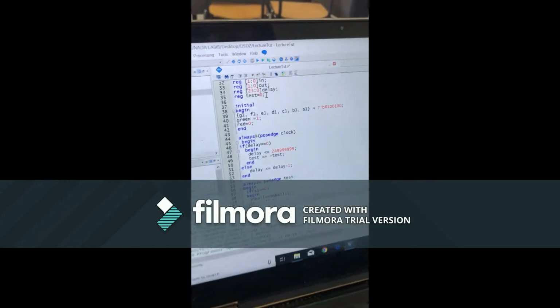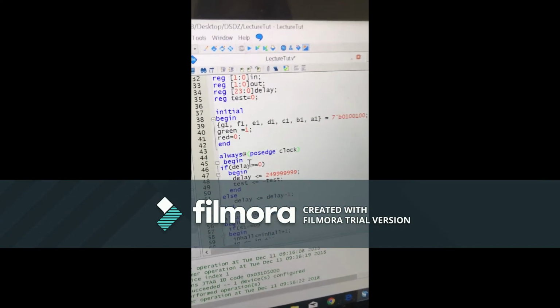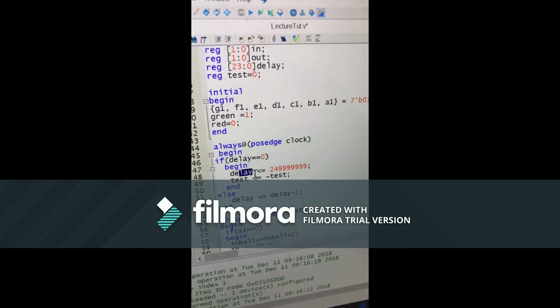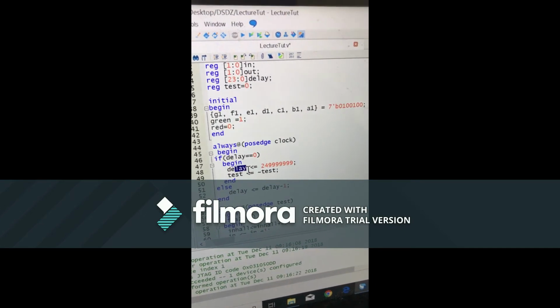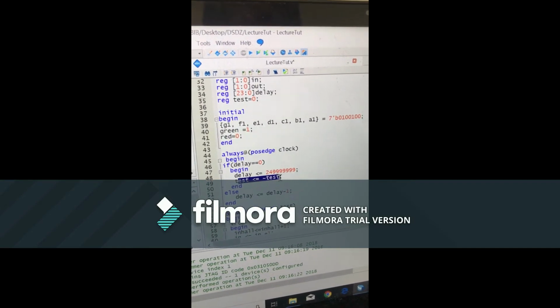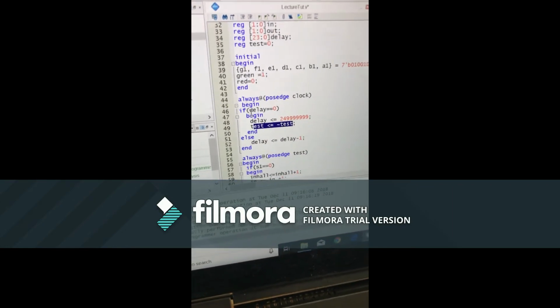First of all, we have initialized a new clock named test. Then, at every positive edge of the clock, we check if the delay is equal to 0. We initialize the delay again to the value we have gained from 50 MHz times 0.3 seconds, and then we toggle our new clock, which is the test. Else, we decrease the delay by 1. And then the always block runs again.